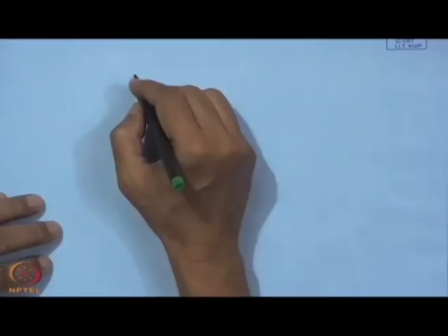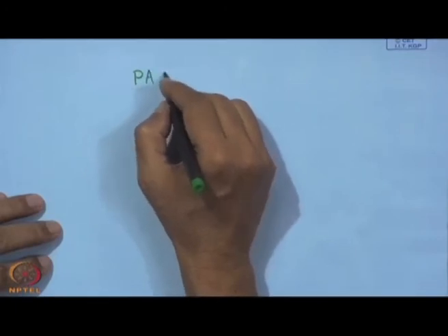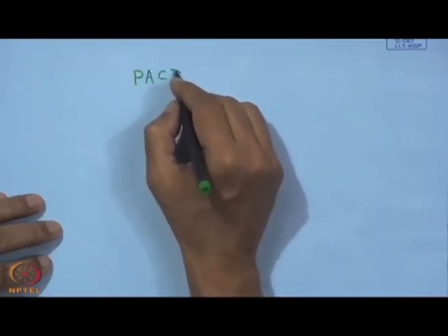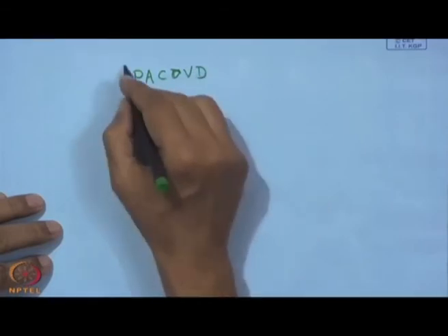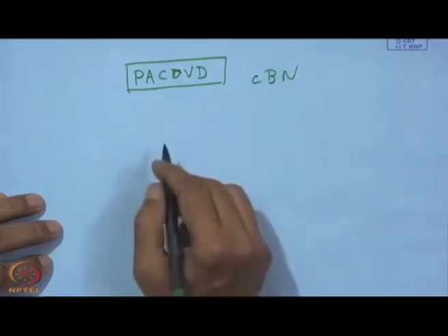In that case, we expect conversion of this boron and nitrogen into boron nitride, and with this high energy impingement that will assume a cubic structure. Now, what we can show here is actually the use of plasma enhanced CVD of CBN. So, what is done in this case?